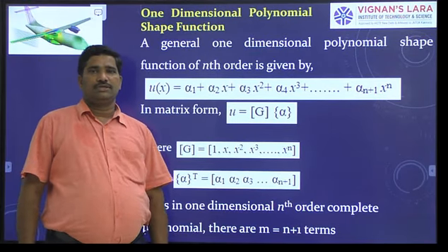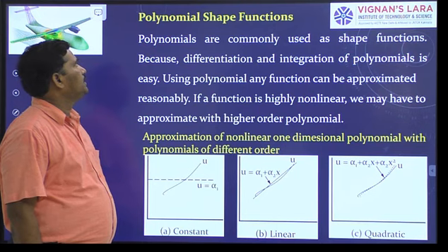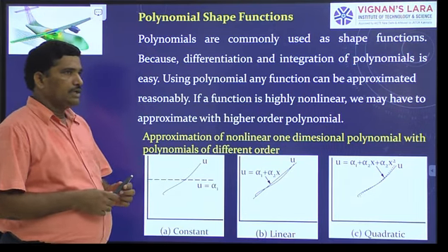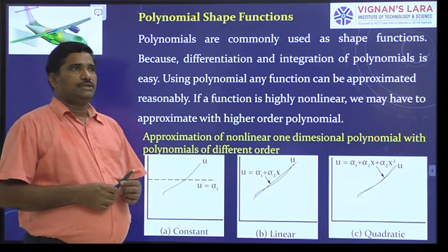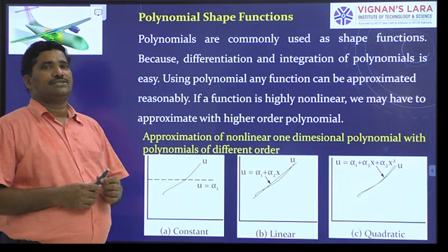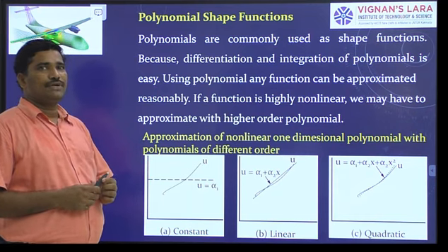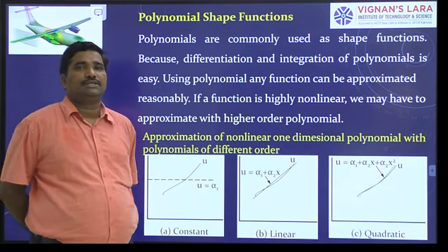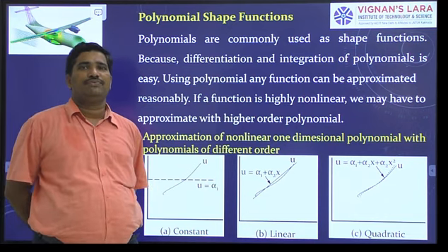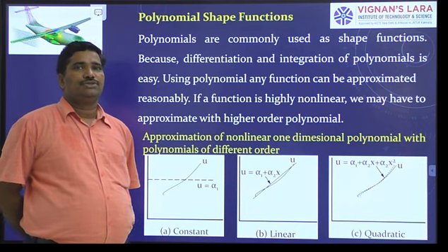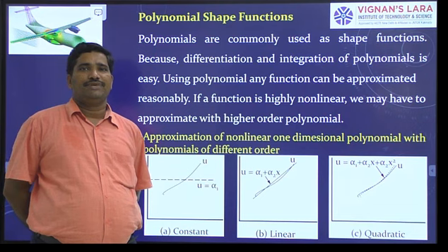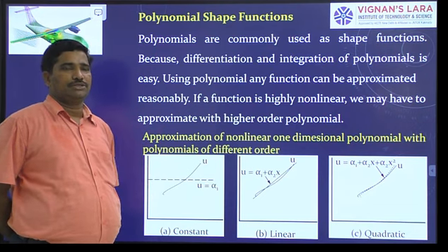Good morning, dear students. Today we shall see polynomial shape functions. In last class we had learned about the shape functions. What is shape function? Shape function is an interpolating function or an approximating function. It is used to interpolate the unknown displacement field with nodal field variables.